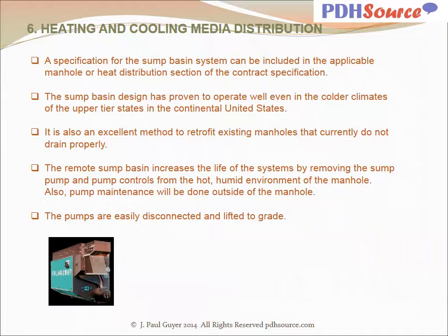The remote sump basin increases the life of the systems by removing the sump pump and pump controls from the hot, humid environment of the manhole. Also, pump maintenance will be done outside the manhole. The pumps are easily disconnected and lifted to grade.